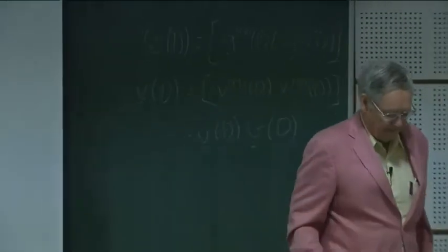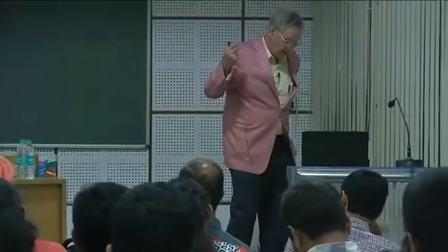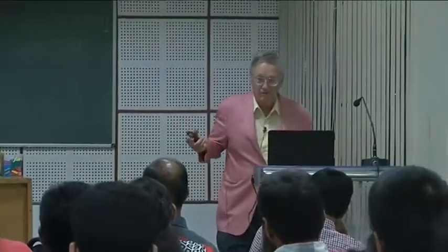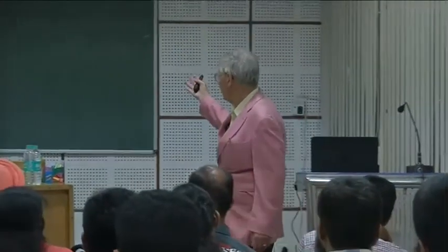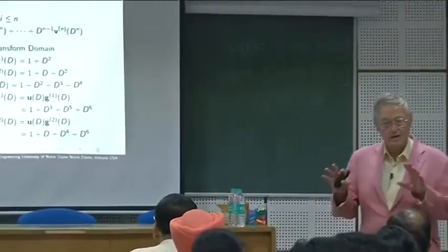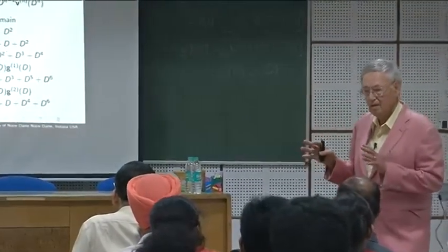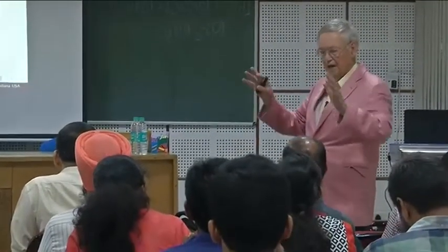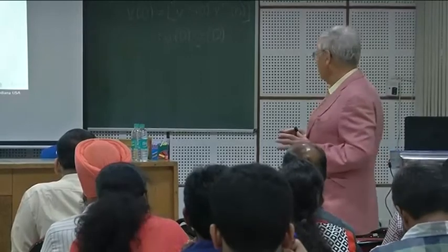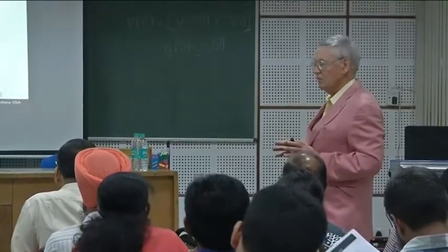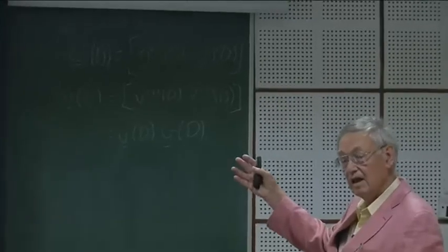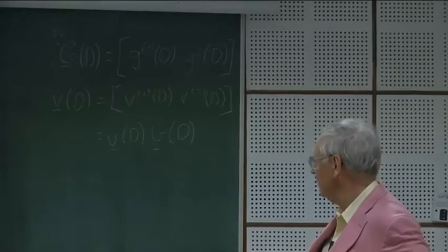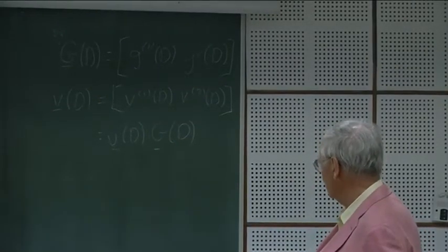So you have not only the binary generator matrix that we showed, but you have a polynomial generator matrix also. It's k by n, 1 by 2 in this case. And in general, you'd fill out this k by n polynomial generator matrix with k times n generator polynomials. In this case, there's 2.